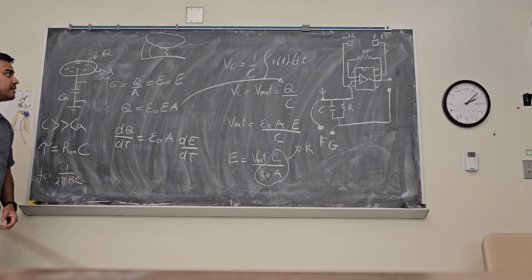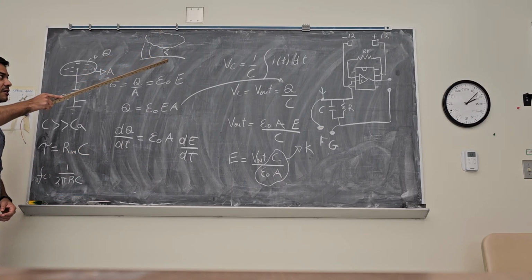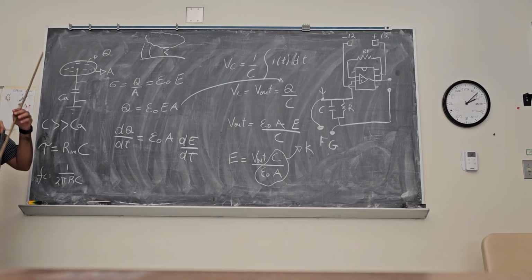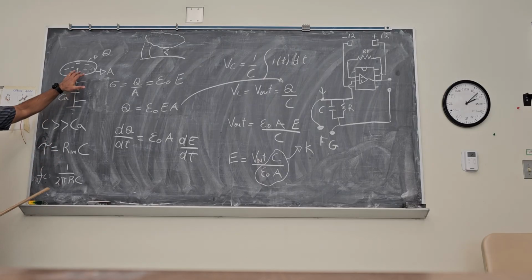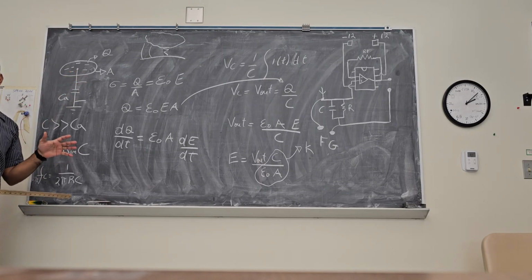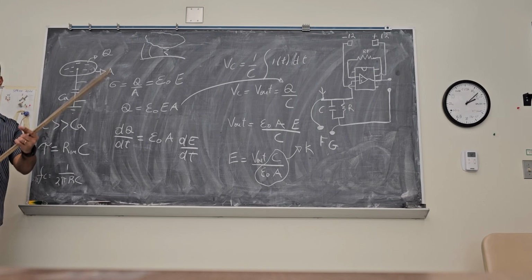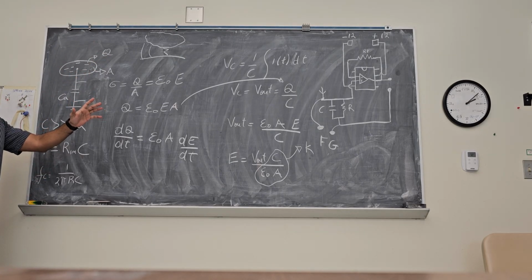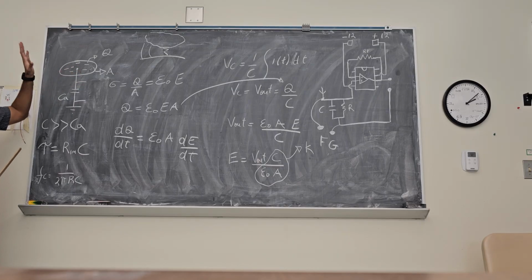Okay? So let's imagine that we have a thundercloud here, and a lightning happened, and then it's going to propagate the electric field in all directions. And at some point you have a metallic probe. It can be a disc, like the ones you have in front of you, or it can be a whip antenna, just a single wire. Okay? So when the propagation of the electric field approaches your metallic probe, you're going to induce some charge in your antenna, in your plate, okay?